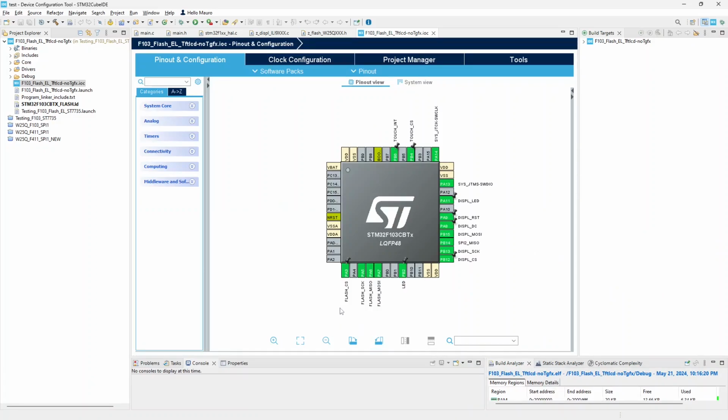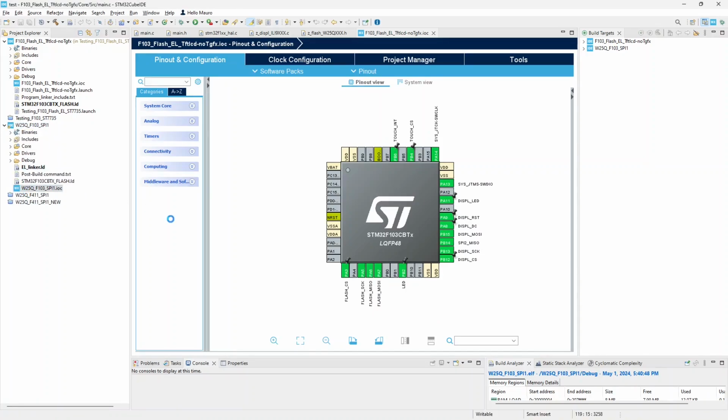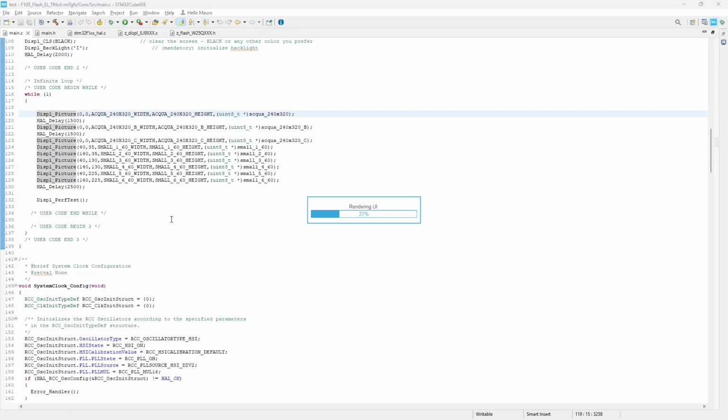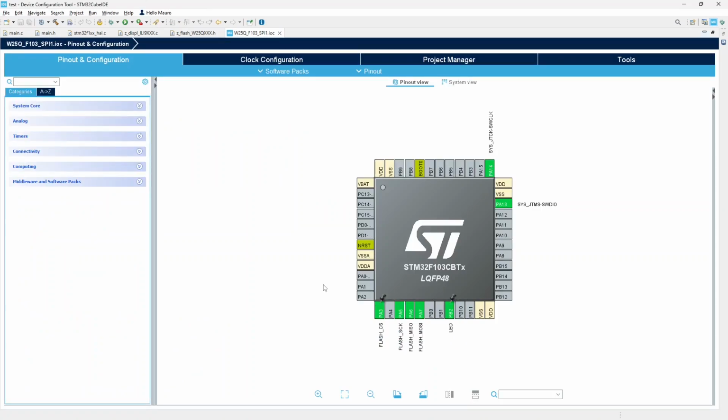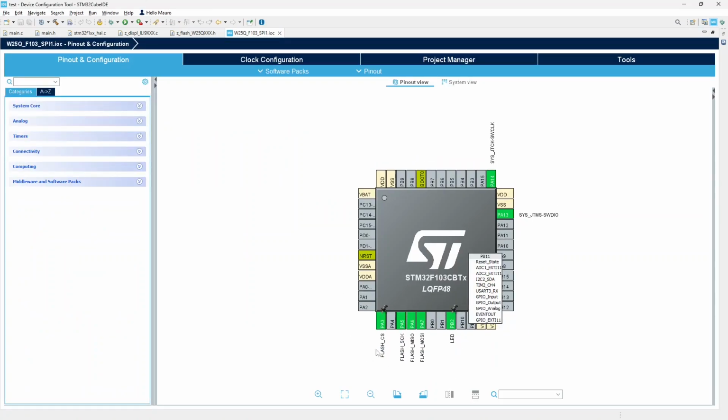Here you will define the exact port to use for Flash and the pin's position, balancing the global configuration needs you have to satisfy. Then, once your design is stable, create a new project. Just referring to the Flash SPI configuration and maybe a LED available, as a simple indicator of the SPI communication running.